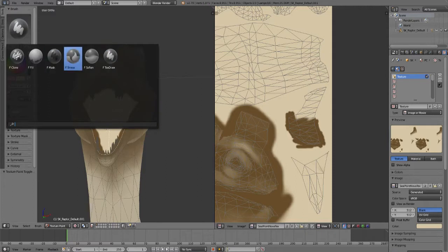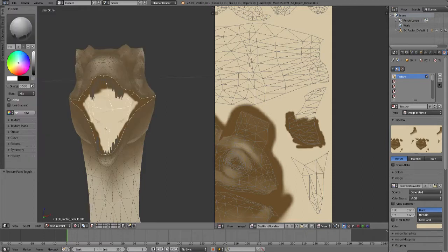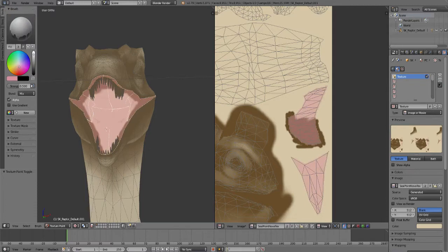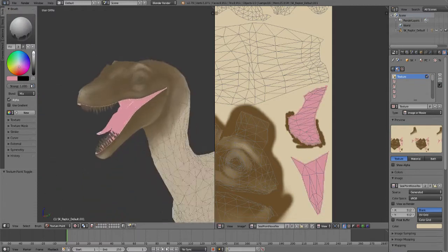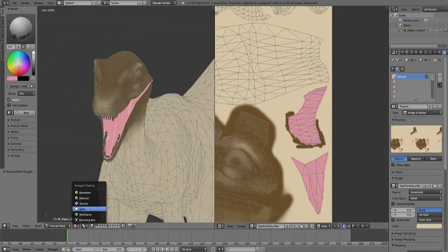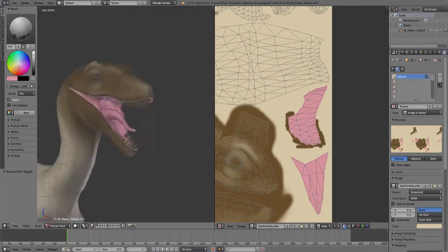Blender has a fill tool. Upon selecting it, your colors will revert to the standard black and white. The strength, aka opacity, is set to 0.5. Remember to set it to 1 before you use the tool. Combining this with the face selection technique will help you lay down solid colors faster, but do remember to clean the edges when necessary.